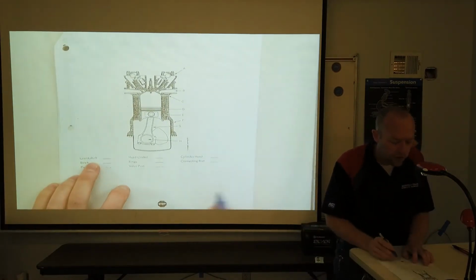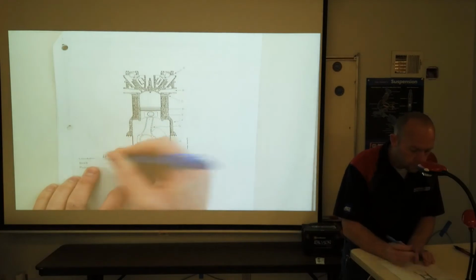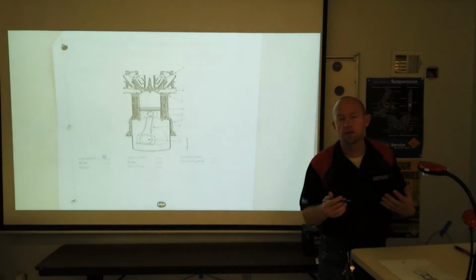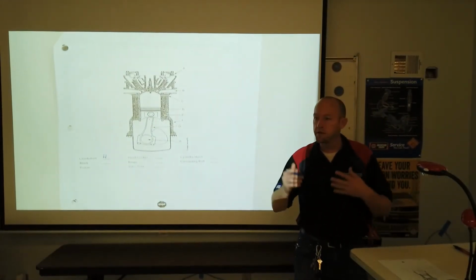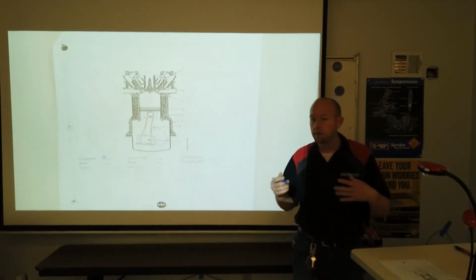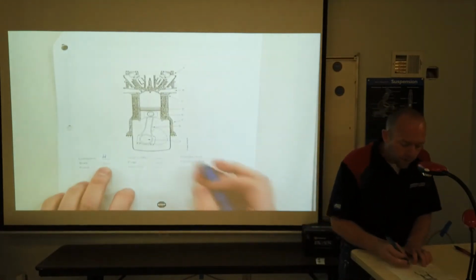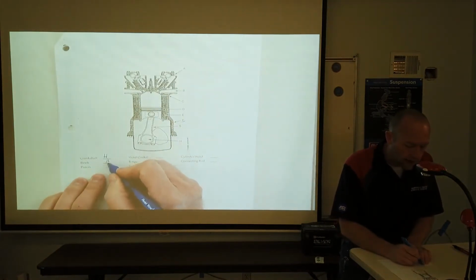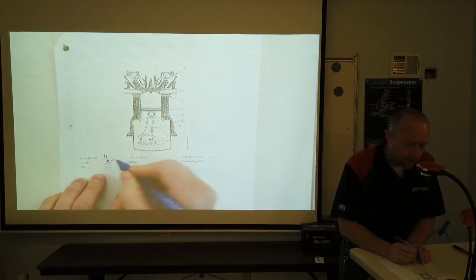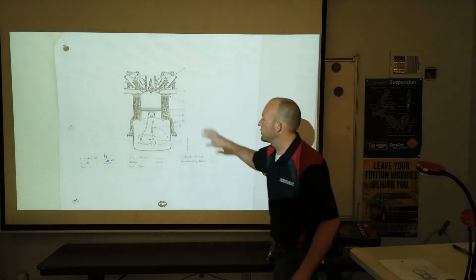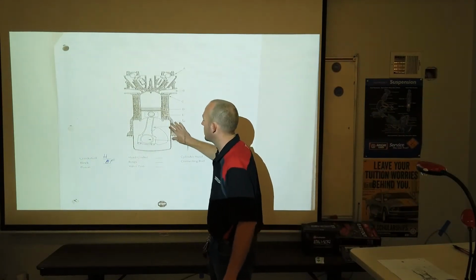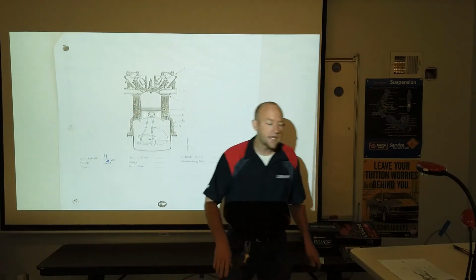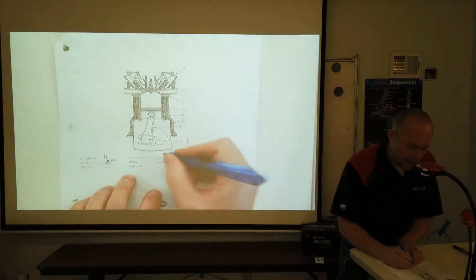So the crankshaft on this would be H. That's our crankshaft. The piston connects to the crankshaft, and we always want to associate the crankshaft with the pistons, and the camshaft with the valves. Then with our block, F right here is actually the block. B for block. So F is the block. And it's more than just what it's pointing to there. This is the bottom end of the block, but our block goes all the way up to C, which is the head gasket.